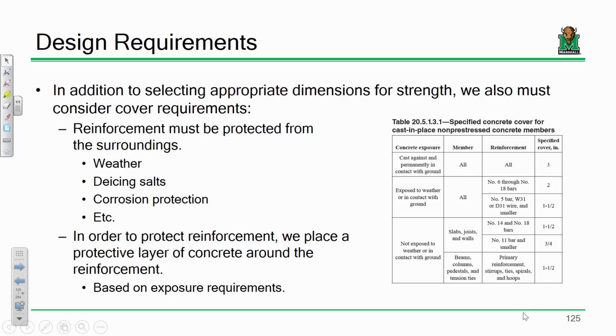Okay. So I guess the overall point I'm making is that dependent upon your application, your cover can change. For example, in West Virginia, for bridge decks, the cover on the bottom of the deck is 1 inch, but on the top of the deck is 2.5 inches. In other words, here's the driving surface, here's the tires, the rebar has to be 2.5 inches below the surface.